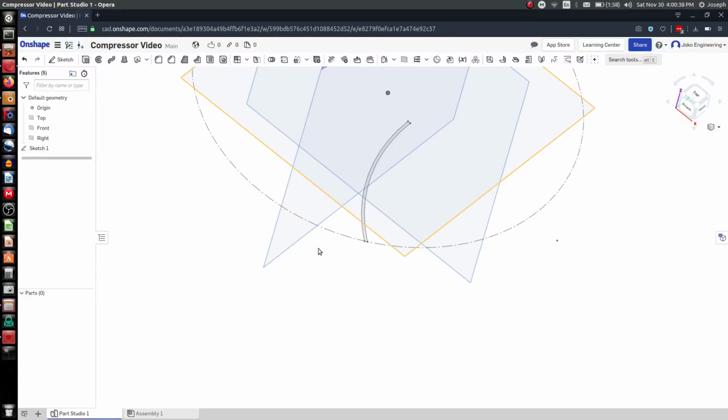Now if I highlight the circle, you'll see that it's driving geometry, but I can use this button to switch it to construction, just like in FreeCAD. Now I can go to my 3-point arc. Oh, but that didn't quite come in the way that I wanted. Again, arc. Kind of a cool relation you don't see in FreeCAD is you can highlight these two and choose concentric, and it merges the centers of those arcs for you.